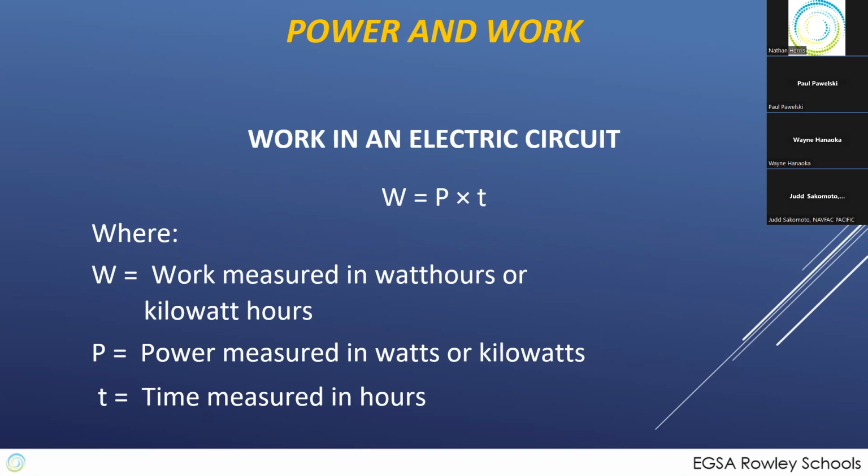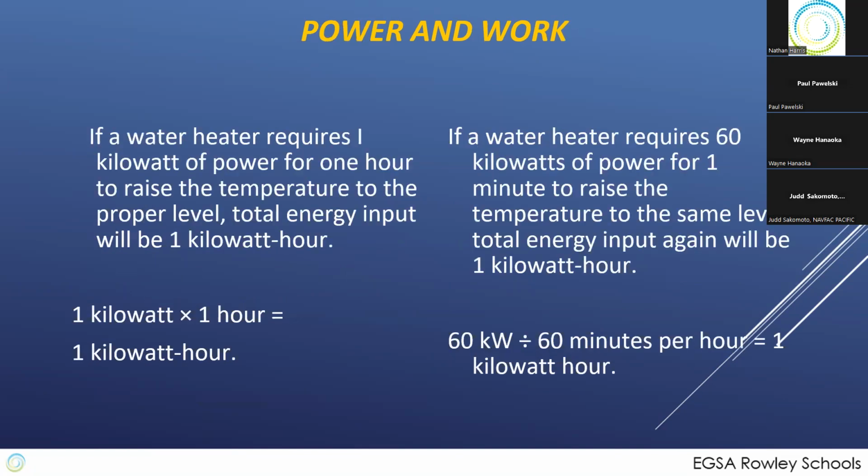All right, well, besides power, there's work, which is just power times time. And as far as electricity is concerned, you'd think 1 kilowatt times 1 hour or 60 kilowatts times 1 minute will both equal 1 kilowatt hour. This is true, and this is why you got the big surge now in instantaneous water heaters. And while the circuits inside the heaters are designed to take the wattage rate that you're running into them, your cables running to them are not necessarily designed that way.